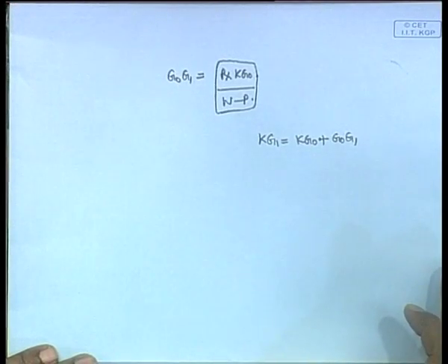Everything we know, P is, again I told you, the displacement at every draft. So this needs the hydrostatic curve again. You look at the hydrostatic curve, you have the draft, and for the draft you read the displacement directly from that curve. When the draft keeps decreasing, your total displacement will keep coming down, and from that you get this W minus P.